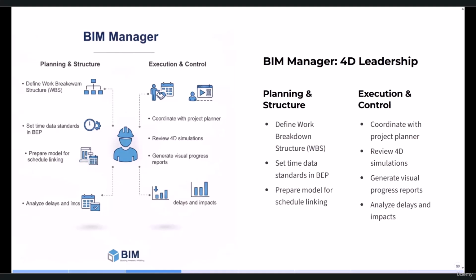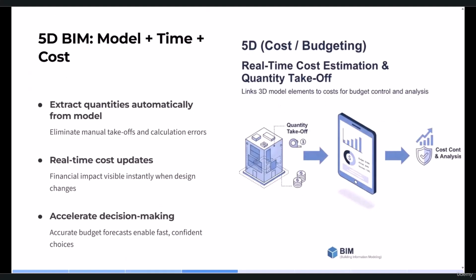So the next item will be specifying the time data entry standard in the BEP, where it has to make sure that the model is ready to be linked with the time schedule. So it has to be coordinated and matched with the project planner. It has to be checked by the modeler that the elements of the model have time or schedule parameters, and it has to review these simulations and analyze the delay scenarios. And finally, it has to prepare and give the reports, visual reports of course, to the manager of the project. So the BIM manager is responsible that the model and, we can say, reality or schedule should always be aligned.